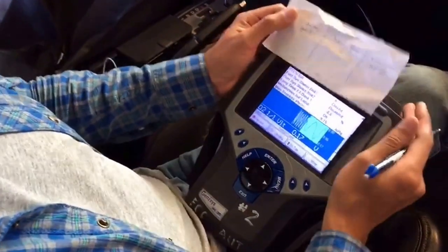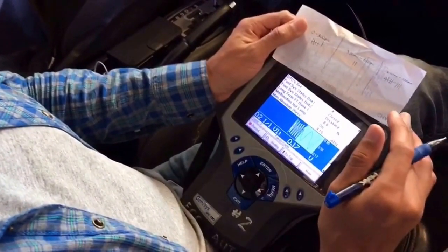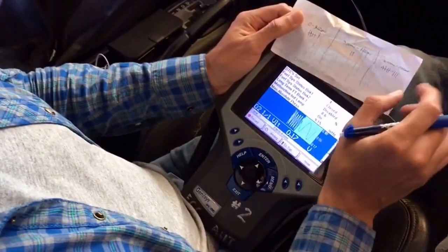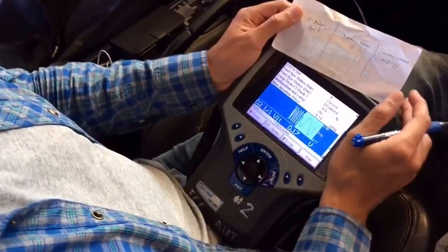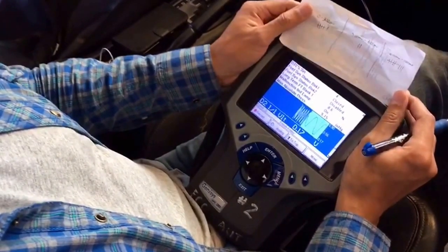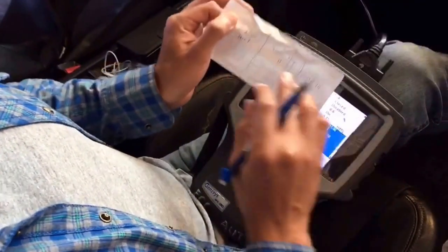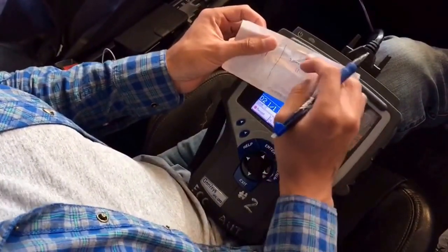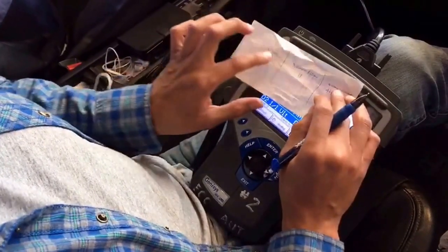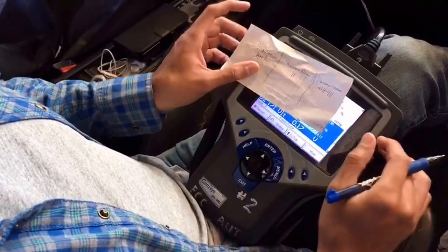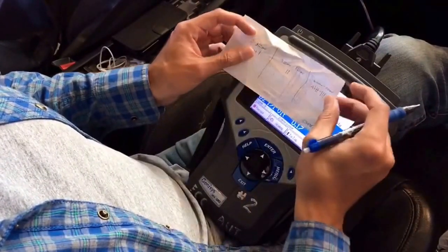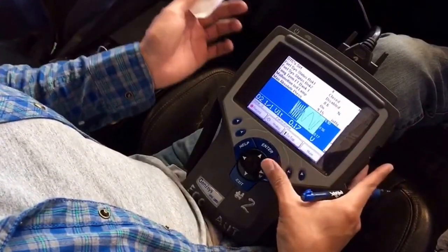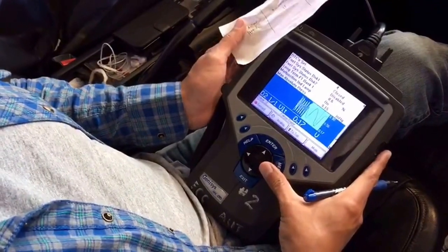Now what all this means is that anything on the opposite sides is good. The more voltage you have on the right side and on the left side is better. That equals a good oxygen sensor. Notice how I have very few tallies, very few voltage signals coming from the middle. If I had more in the middle than any other place on the sides, that would mean I would have a bad oxygen sensor. So basically that's how you check an oxygen sensor upstream using a scan tool.